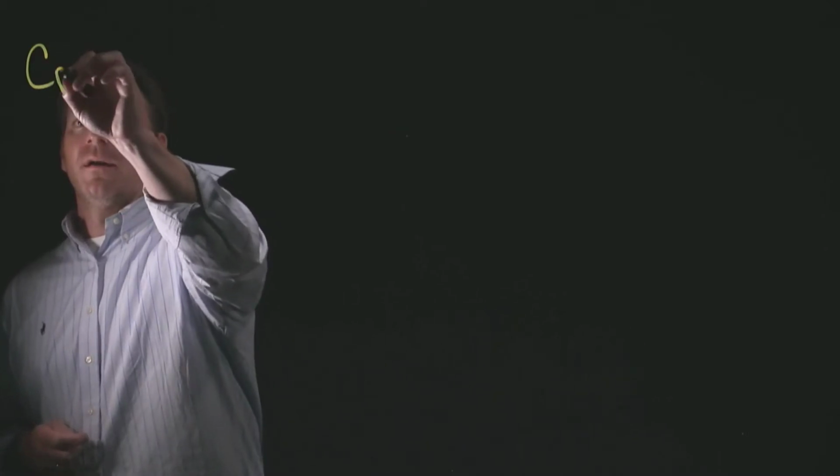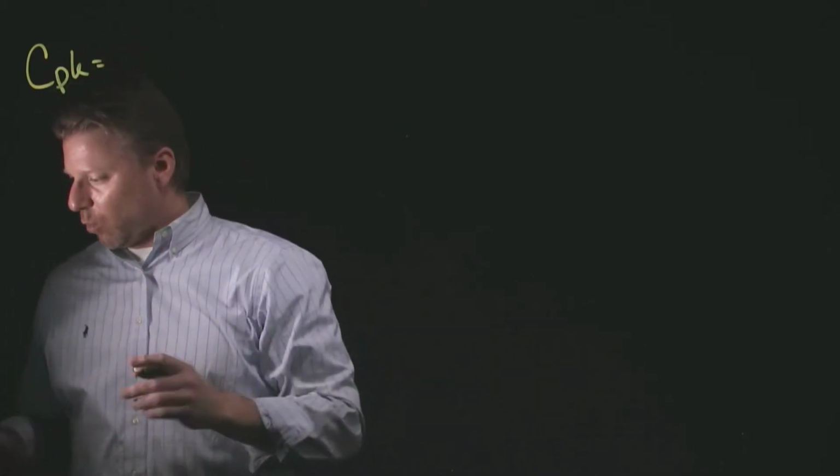So in our last video, we calculated a process CP and CPK to start to understand how what we were doing was meeting our expectations. Very generic way of saying it. We're going to go one step further in this video by saying we can now calculate an expected PPM. And the reason for this is if we say to somebody, our process capability equals